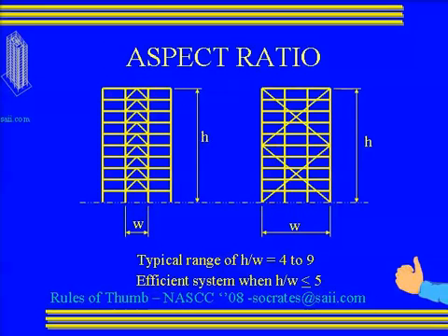Aspect ratio of tall buildings. The aspect ratio of a building is usually always reported as the height of the building divided by the width. But in reality, if you had a system like the one shown on the first sketch there, and assuming that those connections beyond the truss panels are not moment connected, then the width is only the width of that braced element.